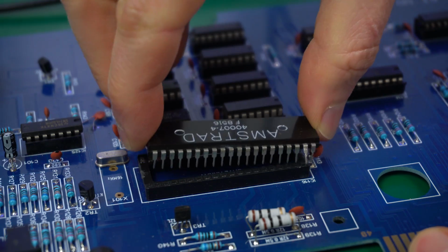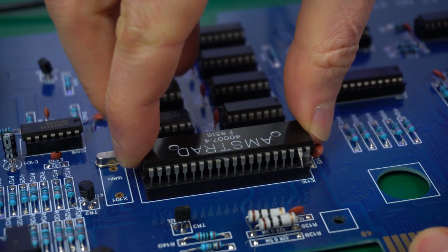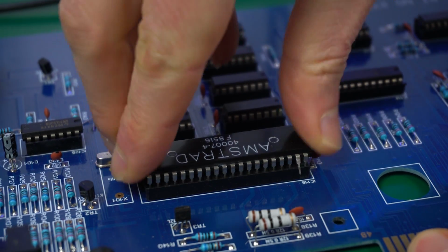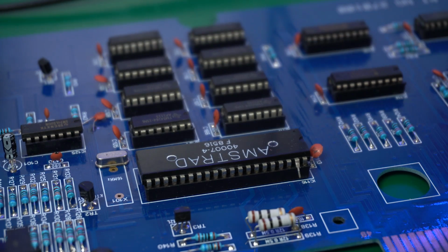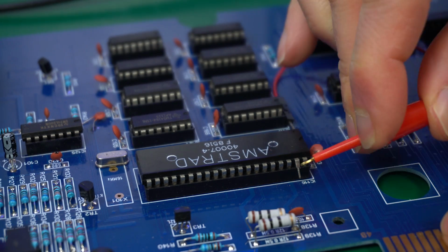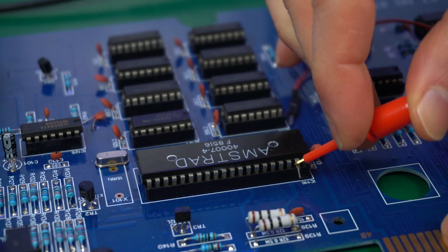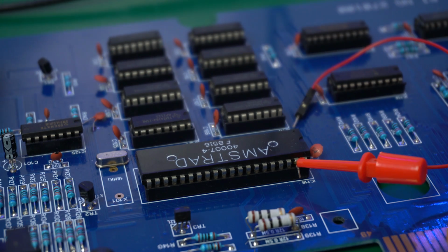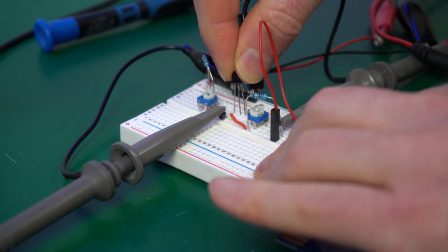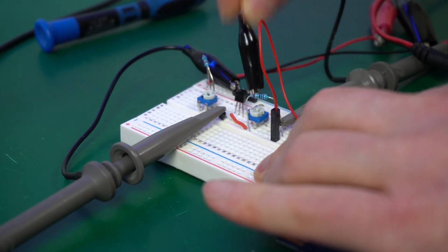Okay, so now it's time to take all this knowledge and put it back into practice to accomplish our original goal, to replace the clock signal transistor on the Amstrad CPC board. I want to try the transistors with the Amstrad, but I don't want to solder and unsolder them all, so I'm going to feed the signal from the gate array into our breadboard directly. I'll just carefully bend pin 39 so it doesn't connect to the rest of the board, and we can send that signal to our transistor inverter. We'll start with the BC547 just like before.